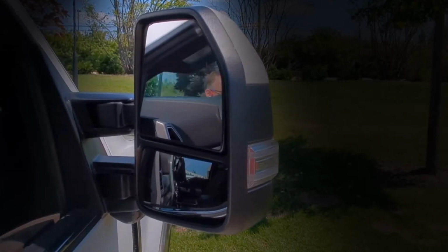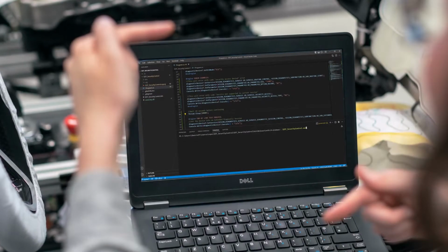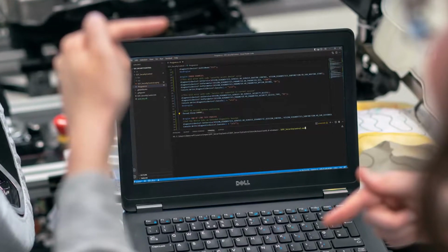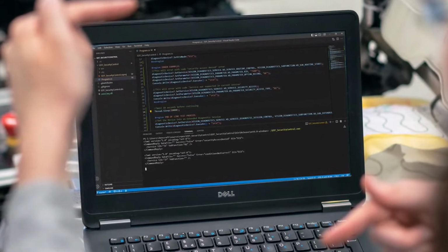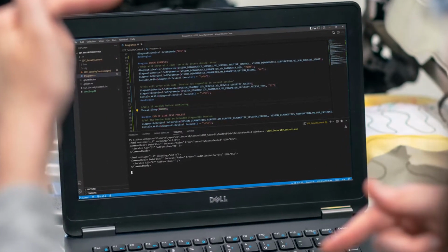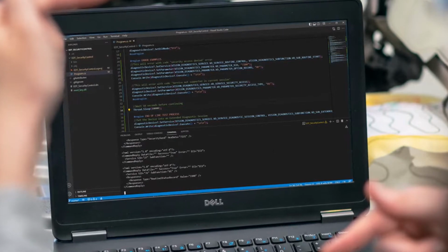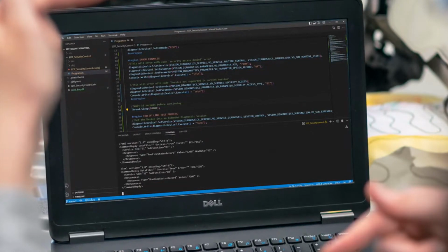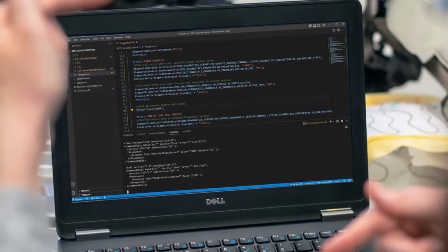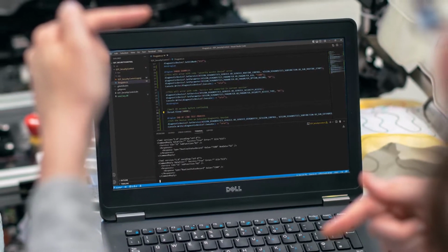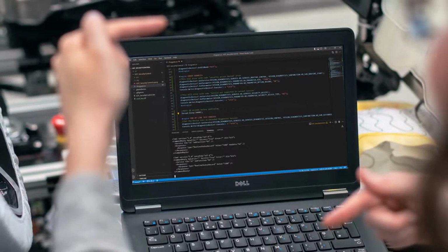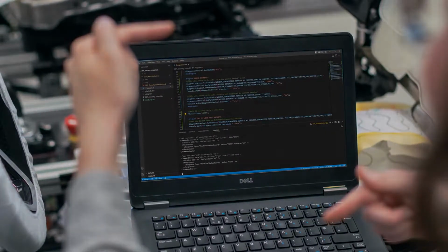By sending a bit-encoded value of 4 ones, or 0F in hexadecimal, the 4 relays are triggered. The ECU in this example requires security level 1 to run this specific routine. To access the security access service on the ECU, an extended diagnostic session is required. For this reason, both Service 10 and Service 27 will be utilized in this demonstration.